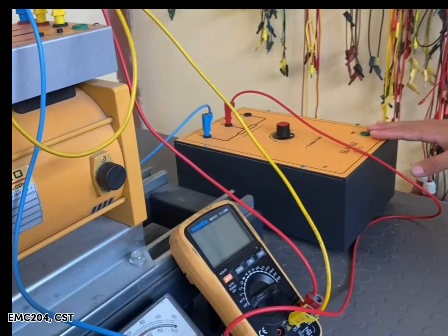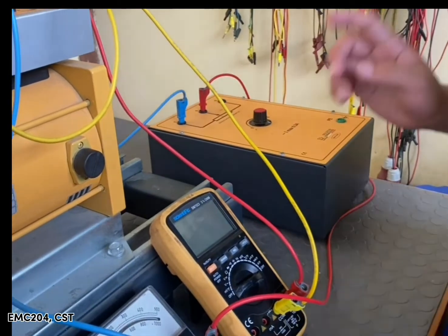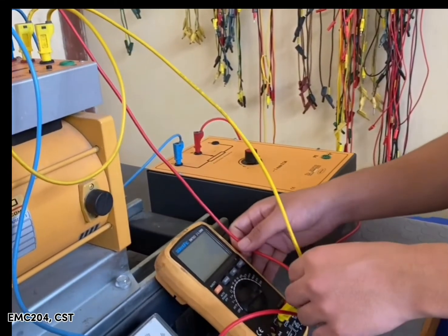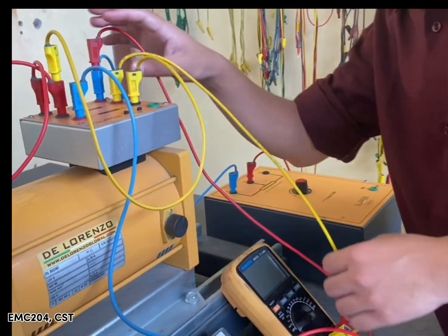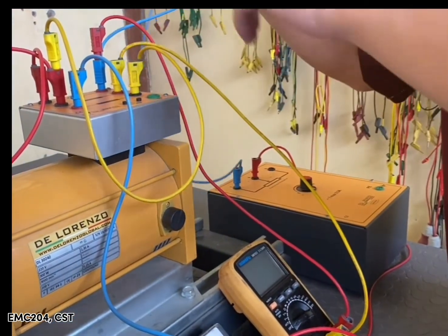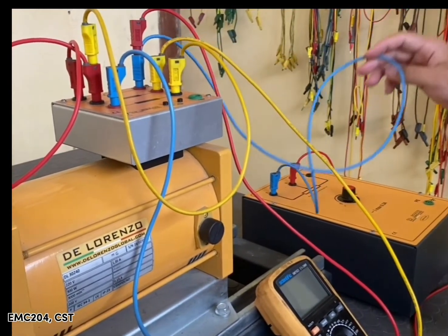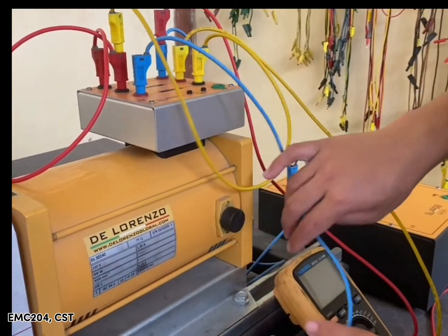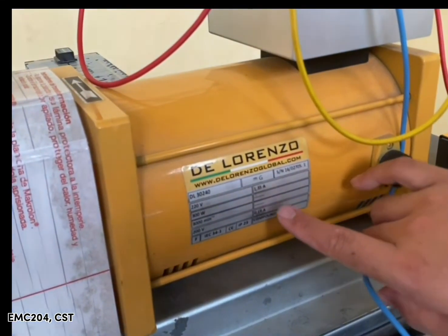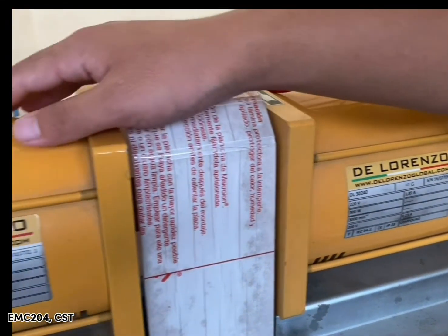In case of generator side, we must maintain the rheostat at maximum. And to measure the field voltage, we are connecting a voltmeter here, and the positive terminal of the voltmeter is connected to the A2, whereas its negative terminal is connected to the D2. And from the A2, we are connecting it to the rheostat. And we must remember the rated voltage and current at generator as well as in the motor side.